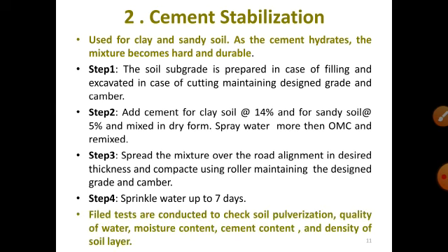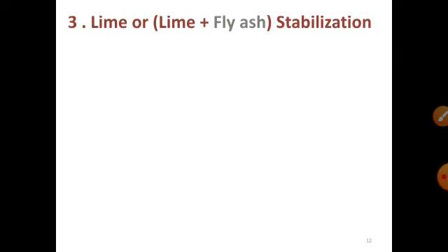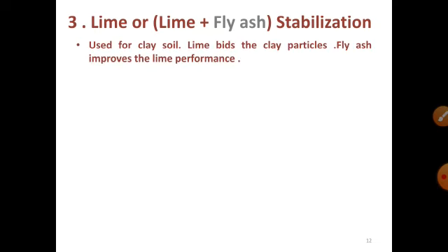Field tests are conducted to check soil pulverization, quality of water, moisture content, cement content, and density of soil layer. Third method, lime or lime plus fly ash stabilization. This method is used for clay soil. Lime binds the clay particles and fly ash improves the lime performance.